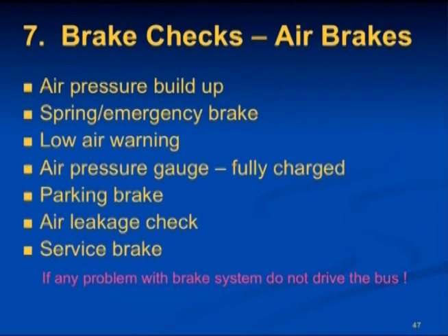For the parking brake check, with the parking brake on and the engine running, place it in gear and accelerate lightly, and the bus should not move. With air leakage checks, start with a fully charged system, the engine off but ignition on and the brakes off. It should not lose more than 2 psi in 1 minute. Apply the service brake fully, and after the initial drop, you should not lose more than 3 psi in 1 minute. If you have a problem, report it to maintenance immediately.